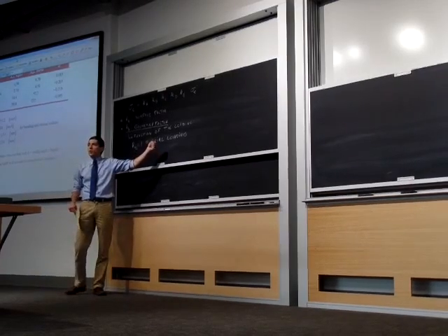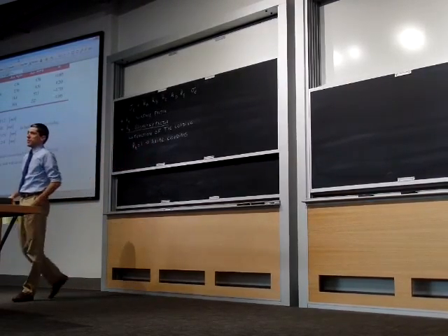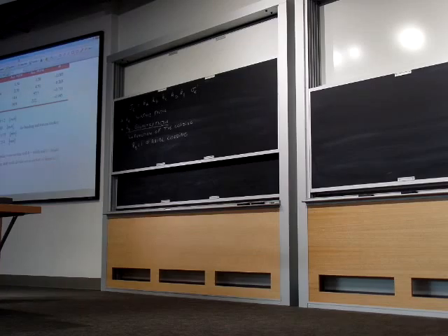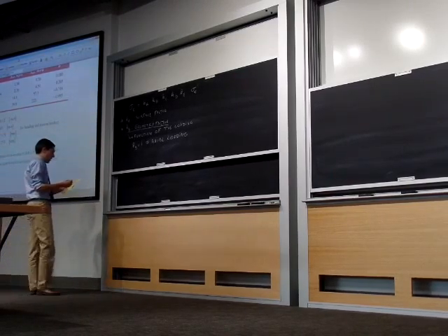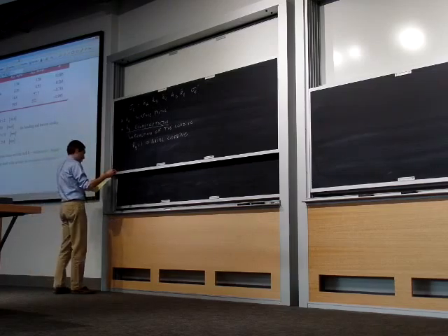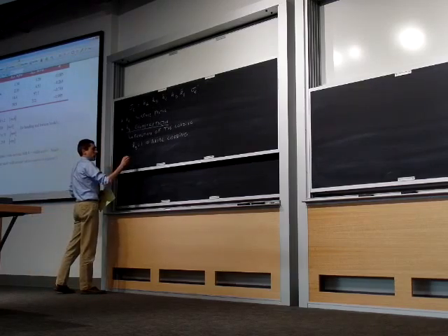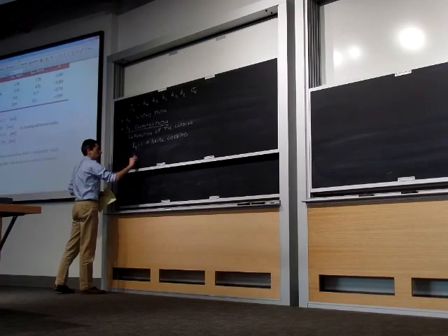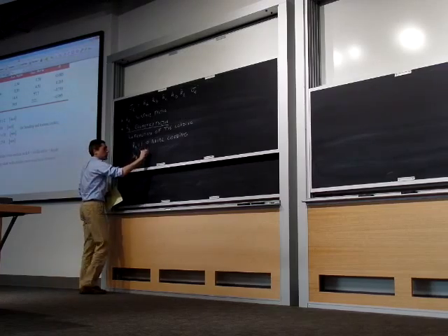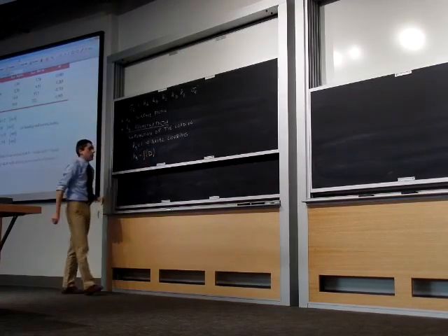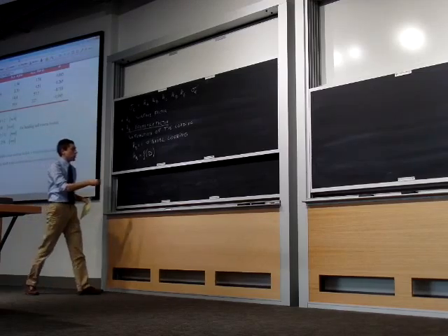Remember, when we talk about loading, in this case we're always talking about dynamic loading, right? We're not talking about static loading because it's fatigue loading. If we have torsion or bending, then Kb is going to be a function of the dimension of that mechanical element, which I'm going to call d.